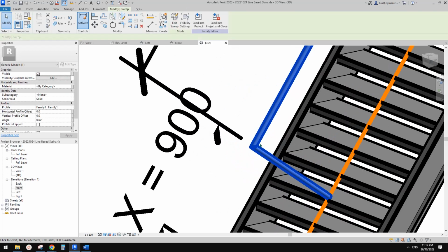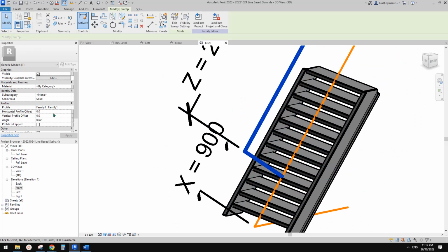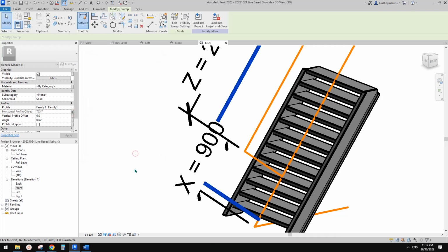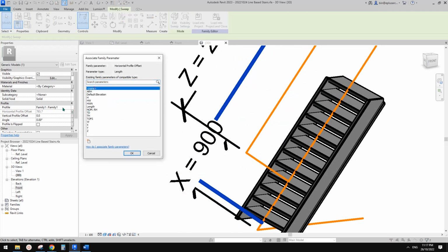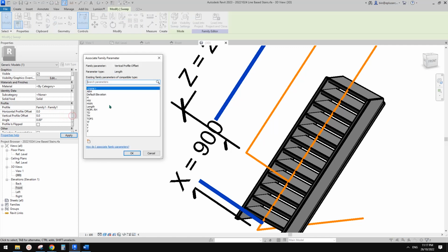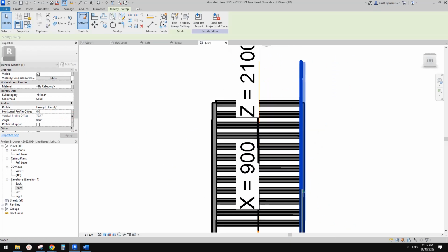So now we can see that's a railing, right? And we can just control the offset here. I'm not sure which one. Let's just try to link the half with maybe this one. Okay, no, wrong. So change it back to none and change this back to 0. So apply the half width to this. So this will offset this railing to here, right?